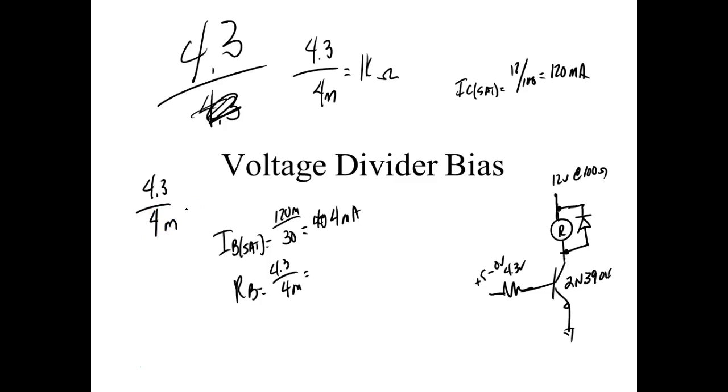So, 1K. Now I could come over here and hook this up to something that provides 5 volts. It's going to be relative to the same common, but now I'm taking 5 volts and running a load that requires 12 volts. So your driving voltage does not have to be the same as your driven voltage, right? You understand that? It takes a little bit of a different arrangement, but this would still be considered what we call base bias.